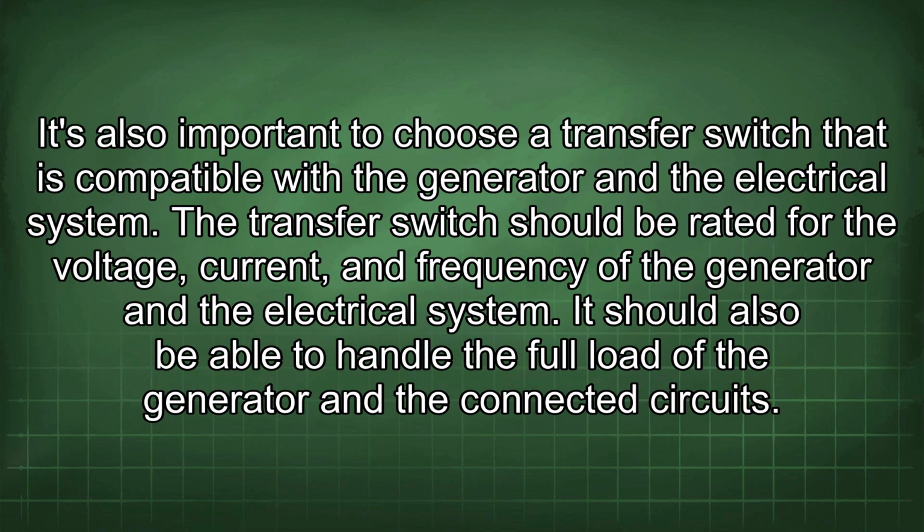It's also important to choose a transfer switch that is compatible with the generator and the electrical system. The transfer switch should be rated for the voltage, current, and frequency of the generator and the electrical system. It should also be able to handle the full load of the generator and the connected circuits.